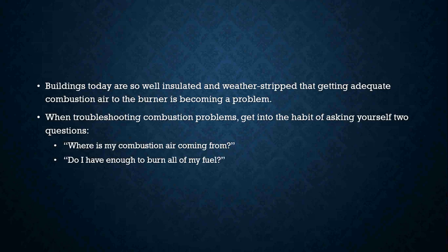Boilers are no exception. Furnaces are no exception. If that building is tightly wrapped and weather stripped and doesn't, quote unquote, breathe very well, we have to have some other means of bringing fresh air into that home. Because if we don't do that, it's going to make the home stagnant and cause air quality issues, but it's also going to screw up how our appliances work, whether that's natural gas or oil.